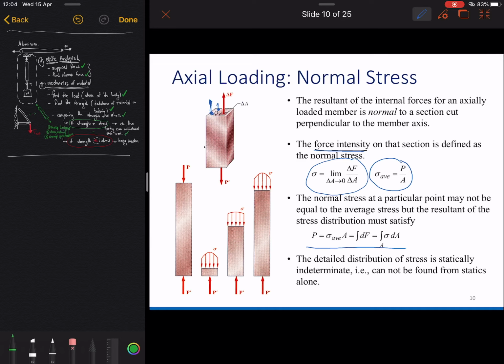You can see it in these pictures. Okay, the force on this side and the force in the middle. The middle has more force, has more stress. It means the middle has more delta force over the delta area, more stress compared to the side. Okay, this is, how to say, the general rule of materials. Normally we will have really high stress in the middle of the bar.